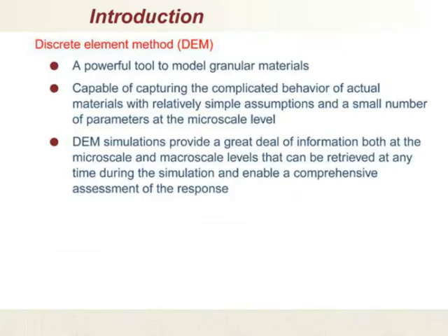So you heard from the previous presenters a little bit about DEM, and this is what I'm going to rely on in my model today, the discrete element method. It's a powerful tool to model granular materials and capable of capturing the complicated behavior of actual materials with relatively simple assumptions and a small number of parameters at the microscale level.